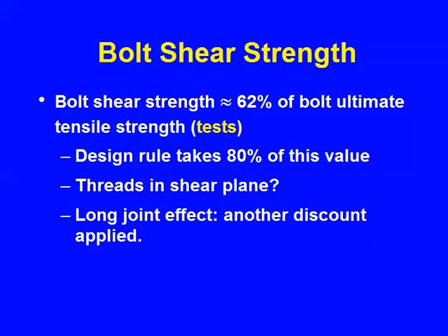And the get together is that the bolt ultimate shear strength is about 62% of the bolt tension strength. The von Mises yield criteria says that relationship should be, and now you do remember, 1 over the square root of 3. Oh yeah, 0.577, 0.58. Well, theory and practice never fit quite together. That's pretty close, and we accept that. I'll show you the type of test that's used to obtain the bolt ultimate shear strength.